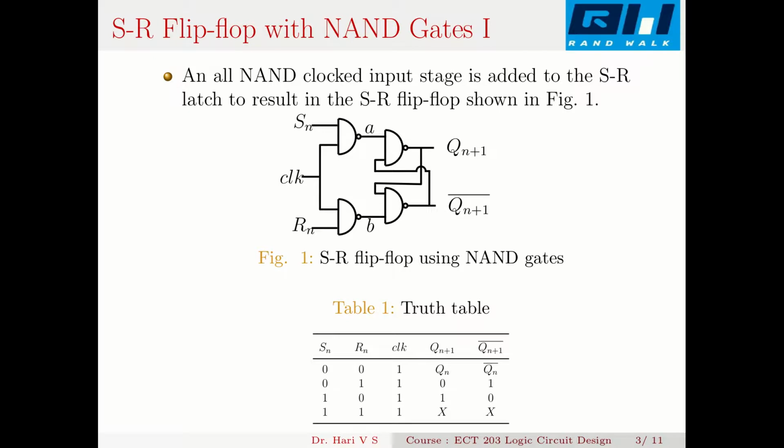Now this is a circuit diagram of an SR flip-flop with the NAND configuration. Earlier, in place of these, we had two inverters. Instead now we put two NAND gates. One input is given at the first NAND, let that be Sn. N denotes the nth clock cycle.